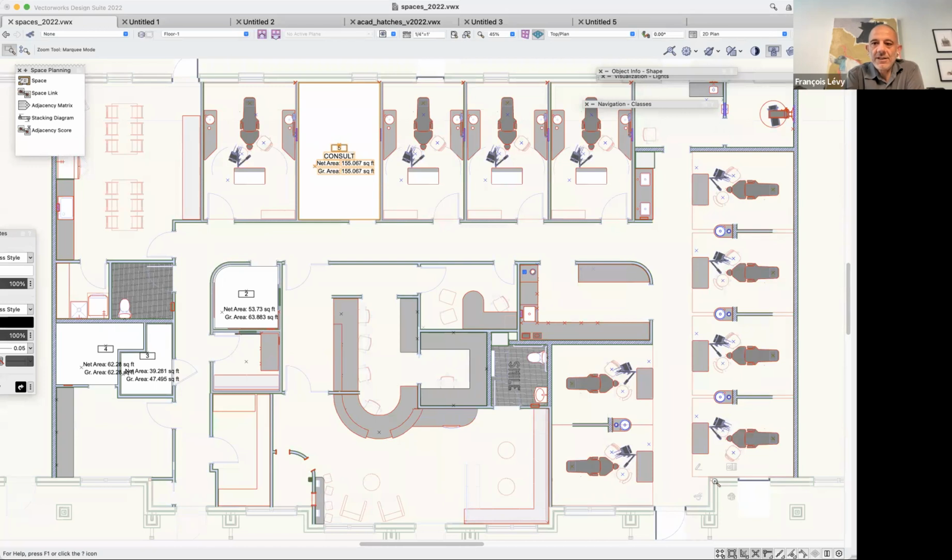It could even have a thickness of 0 or nearly 0 if you had to assign it some thickness, so that you could create a boundary between spaces that you might consider to be two separate spaces, even though the walls would suggest that they're one. Right. So that's another little trick that you can use.